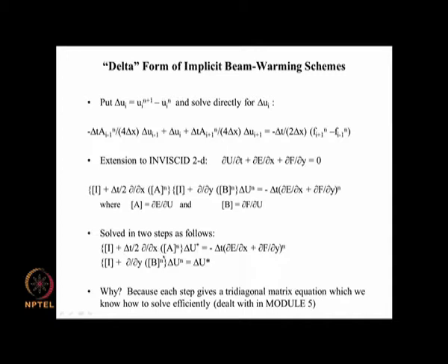So in that sense this is an evaluation of the nonlinearity and coupling based on the previous time step values, and therefore this is called lagging. Okay, lagging. So this particular contribution of the overall equation here is coming based on the previous time step values, whereas this is based on the new time step values.